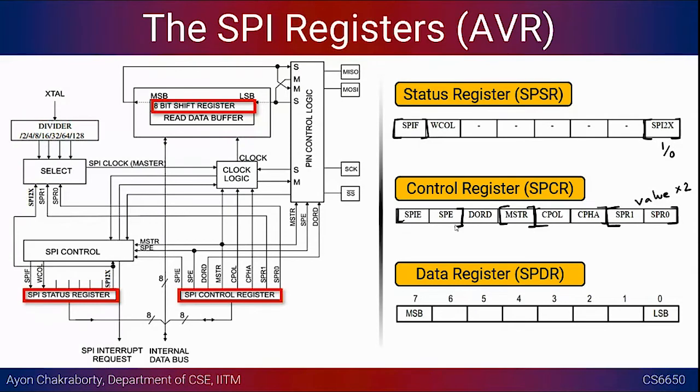The bare metal program or the driver for the peripheral has to be implemented using those sets of registers, right? So understanding these things very well is important, particularly if you want to write efficient code that is adapted to the features on a particular microcontroller.